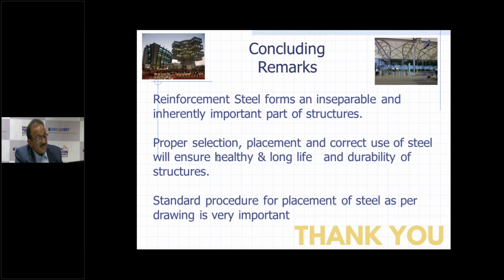But when you use these high strength bars, you have to also worry about the deflections. Normally these high strength bars have a tendency to give more deflections in concrete structures. So one has to be careful, and during the design stage, one has to see that the deflections are within the limit when you use these high strength bars.